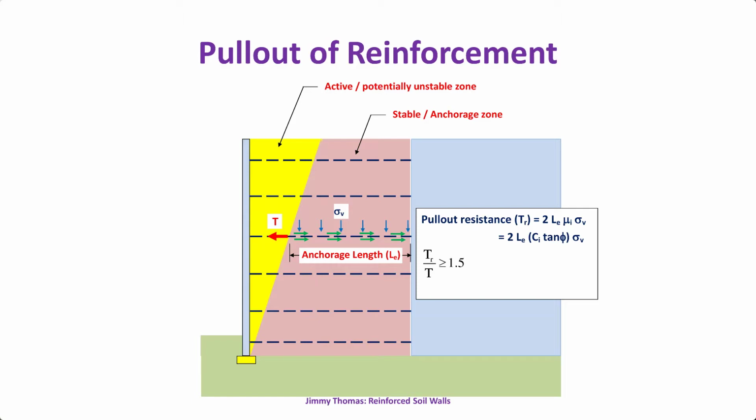So this is simple, depending on the load factor, resistance factor, then each load combination we have to check actually. So again, if the length is not adequate, remember like initially we had checked for 0.7 times height as the trial length. Then we have done external stability. Then here also, if the required factor of safety is not achieved, we have to increase the length.